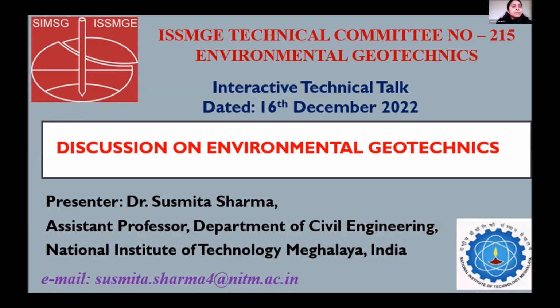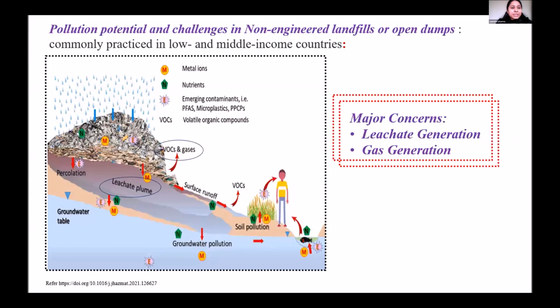As mentioned in the previous slides by Professor Takeshi, from a scientific standpoint, in most developing countries, or countries with mixed economies, even though municipal solid waste landfills exist on paper, in practice we have open dump yards or unsanitary landfills. So what happens in this unsanitary landfill? This is where soil contamination and water interaction take place.